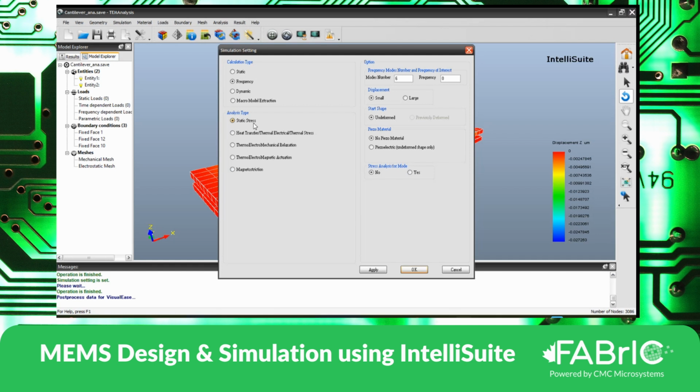But if there is a change in natural frequency due to heat transfer thermal stress, due to electrostatic force, due to the magnetostriction property of the material, then we select based on that physics. So typically thermo-electromechanical relaxation or electrical thermal stress is generally selected when we want to see that the natural frequency would change due to the applied load.